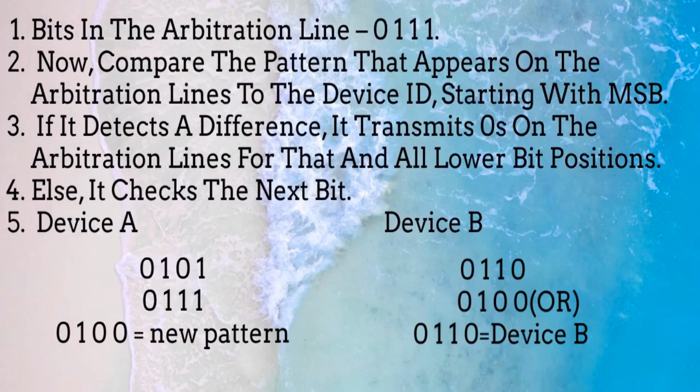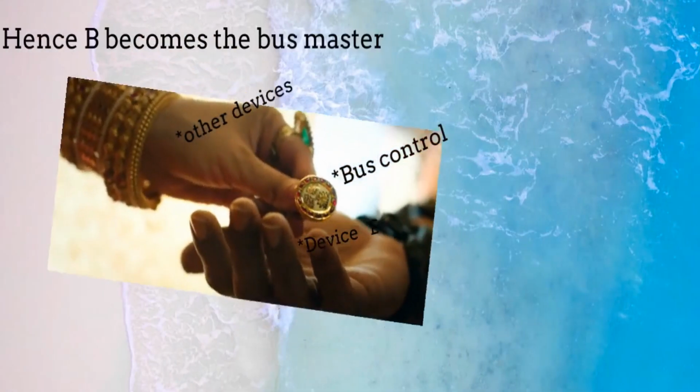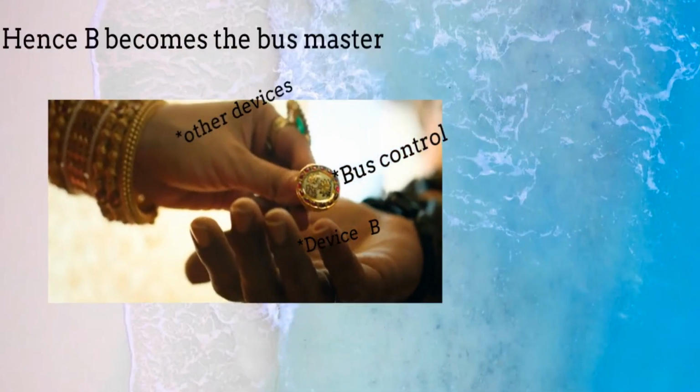Now compare the pattern that appears on the arbitration lines to the device ID starting with MSB. If it detects a difference, it transmits zeros on the arbitration lines for that and all lower bit positions, else it checks the next bit. Here, device A has 0101. When we compare with 0111, we get a new pattern 0100. On device B, 0110, when we compare with 0100, we get 0110. Therefore, device B becomes the bus master.